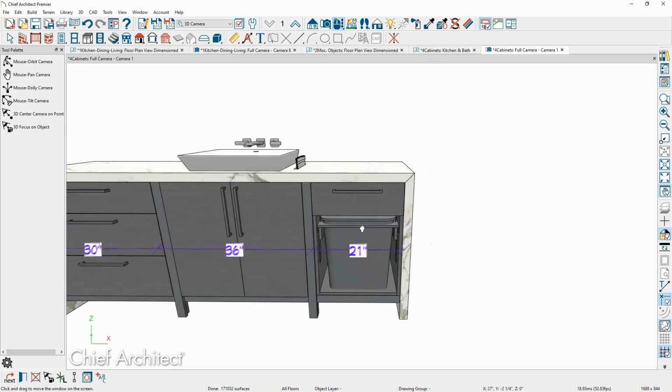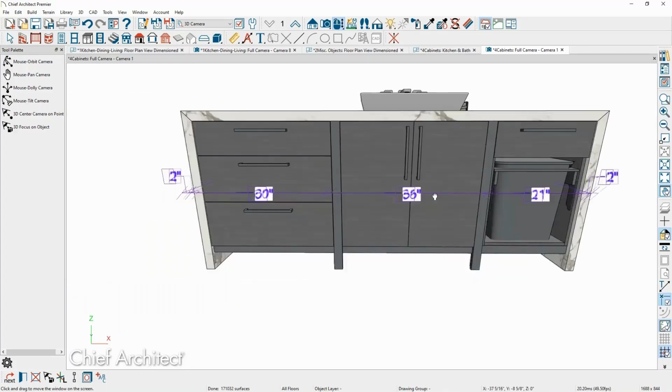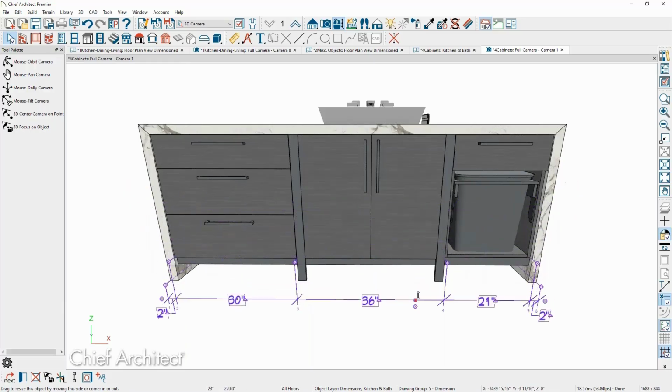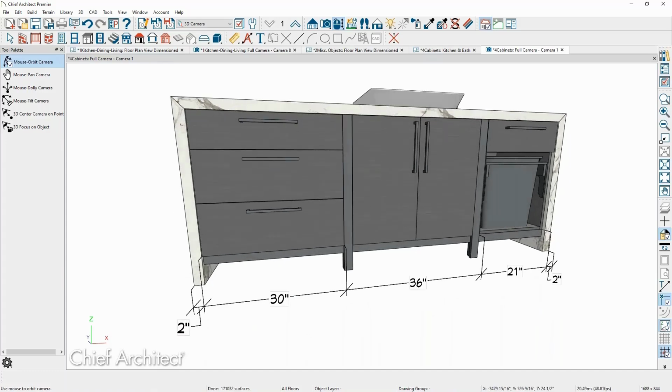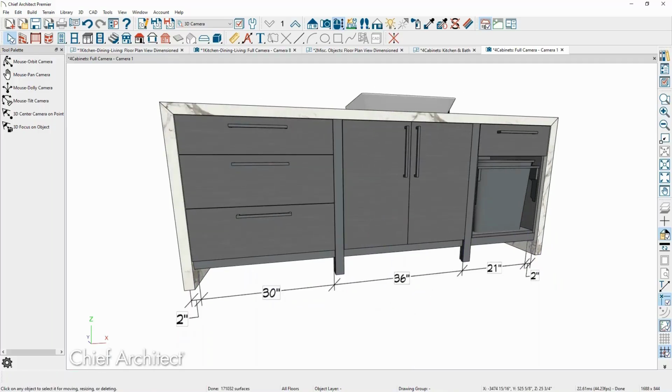And then let's get one more dimension for the other end of the waterfall. So I've got the extra diamond with my string selected. I'll just bring it over there. And then next, let's push it to the bottom by clicking on it, and then clicking the red handle and moving it down till it's about there. And then let's push it back until it's maybe underneath it a little bit. So to do that, I can click on the dimension, click on that handle one more time, and then let me rotate a little bit. So click on that handle, and then use my blue arrows to come back a little bit. That's looking fine for our example.